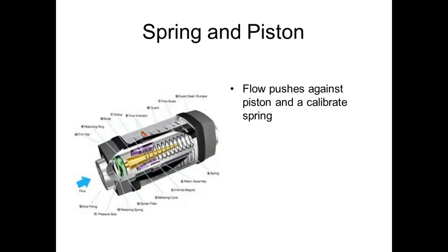Now a reed switch, of course, is digital. Everybody understands that. Hall effects can be either digital or analog. So what does a Hall effect sensor do? Well, it senses the magnetic field, or it can measure the strength, right? So we have an analog Hall effect, which would measure the strength, and then we have a digital Hall effect that trips at a certain strength of the magnetic field. Are we okay? Pretty straightforward how this works.